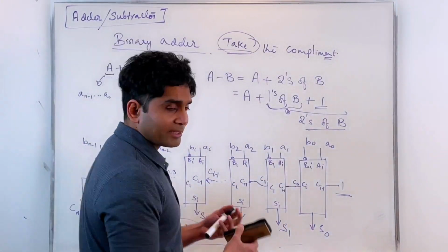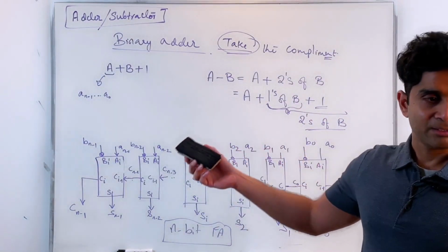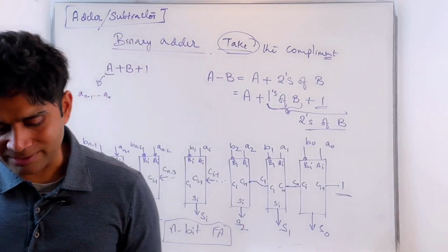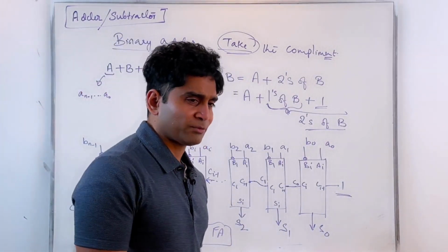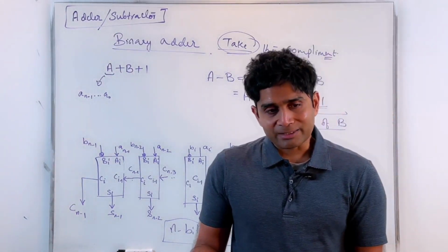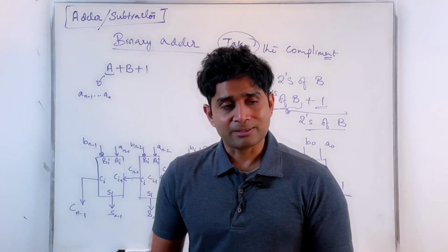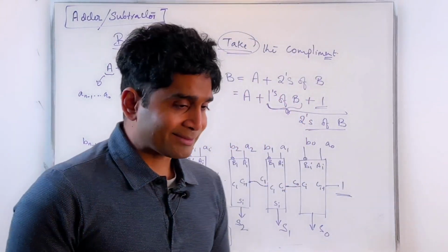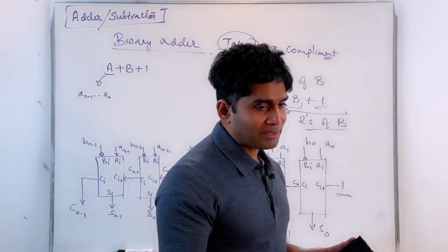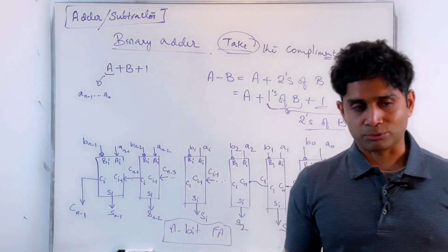So the 2's complement approach really becomes handy here, right? Now, when we initially described the 2's complement subtraction, it seems like a big chore. You'd have to find the 1's complement and then the 2's complement. Then you have to add. You could have done it directly, A minus B operation, like you do on paper. That would have given you the exact same result. And you're taking these additional steps to do this. But now I hope that makes more sense why we want to go the 2's complement approach.